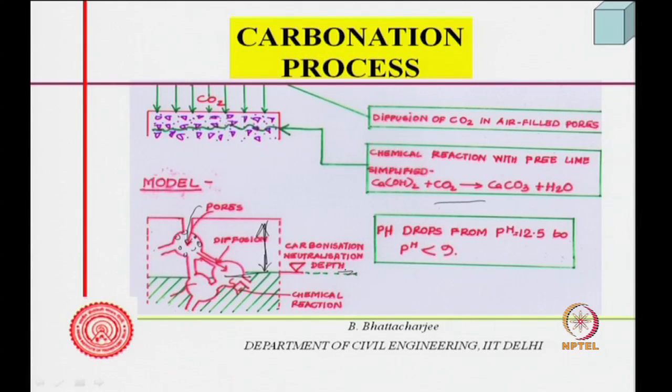reaction has occurred, carbonation, neutralization. So, this is the neutralization depth, and that is the carbonation depth. So, we call it the carbonation depth, up to which all the alkaline material has got neutralized by carbon dioxide coming from outside. So, again the pores are important, the moisture situation is important.